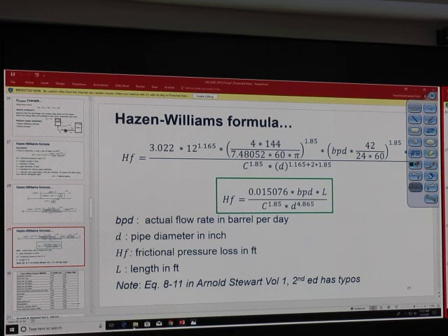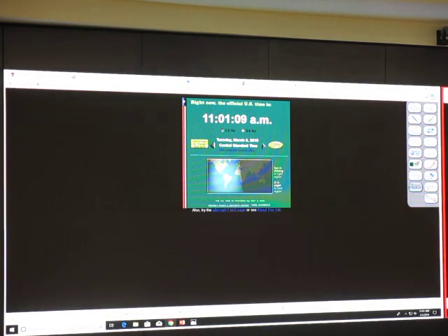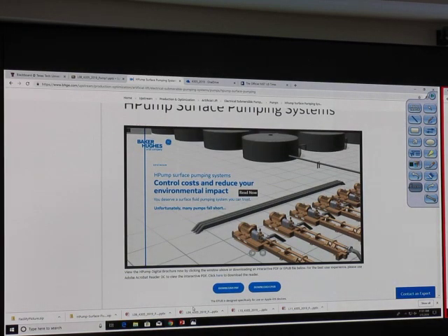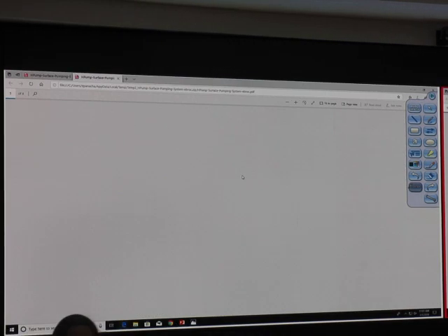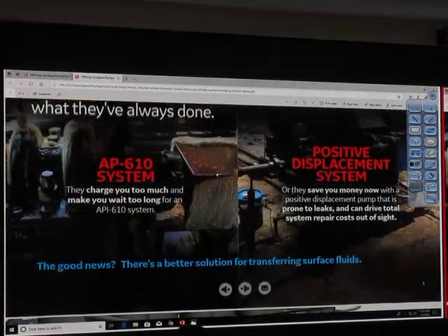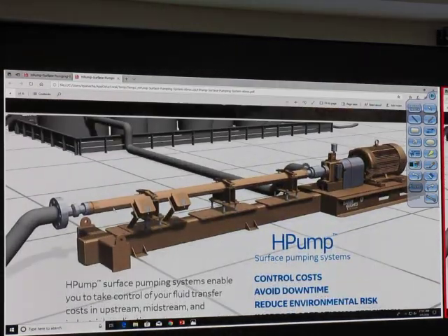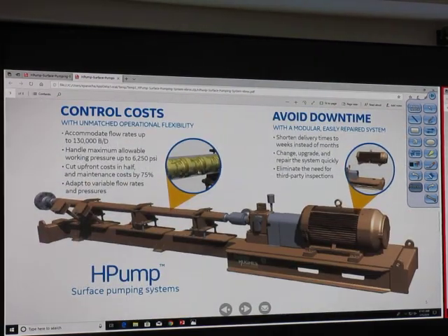Last time I got a question about the H pump. How does that H pump look? I have this picture, and there's something inside the H pump that I can see: it is a multi-stage centrifugal pump. So that is the H pump, and inside it has several centrifugal pumps. We put those pumps in series to increase pressure. You agree? We increase pressure by doing that.